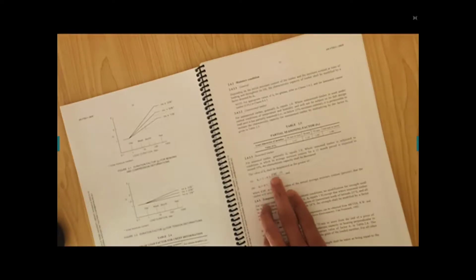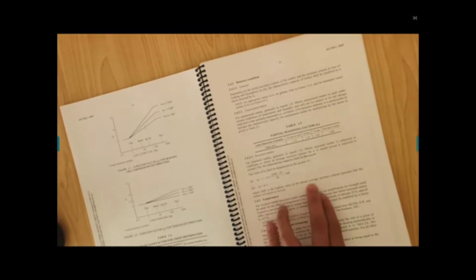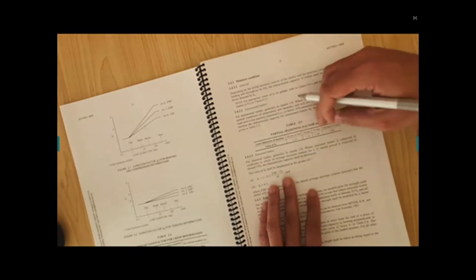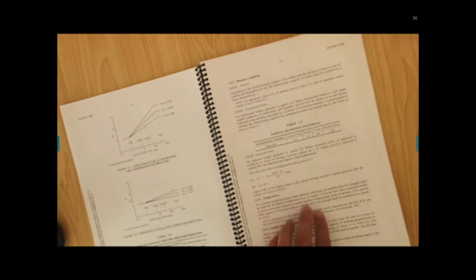One, take away 0.3, you put the equilibrium moisture content here, take away 15 over 10, you can calculate that, or you can take 0.7, whatever the highest value of annual average moisture content percentage that timber will attain in service, right? So it is easy to do. If it is seasoned, you can take it from here, but it is given as seasoned, so K4 equals 1.